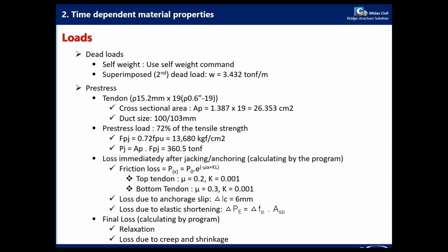And the load we are going to consider in the construction stage analysis, we have the dead load. And you all know that the dead load is the main load that is applied during the construction. So the self-weight of the structure is the main loading. And we have also to apply the pre-stressing force.